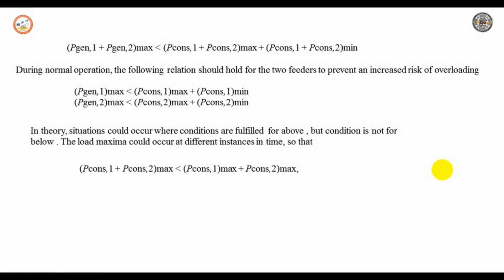Among these are limiting the generator size, reinforcing the distribution network, accepting backup operation, which is not possible in almost all cases, and curtailment of generation during backup. All these are some of the solutions to cope with redundancy in the distribution network. The latter is the most reasonable solution, where curtailment is needed only for the duration of a period with high production